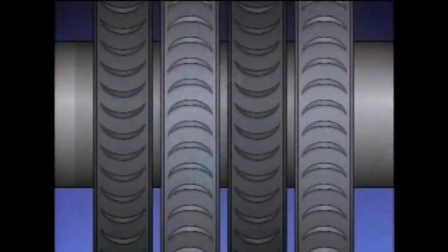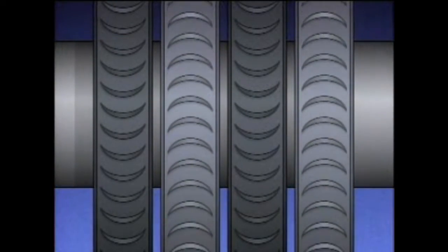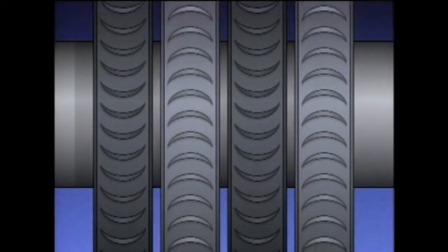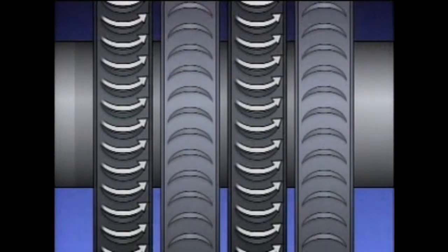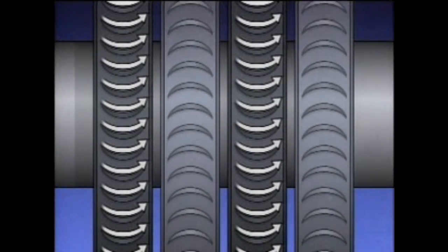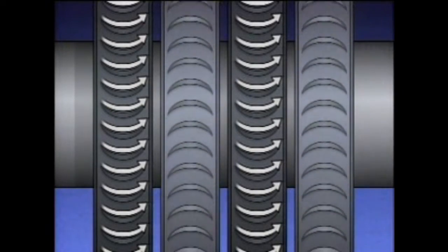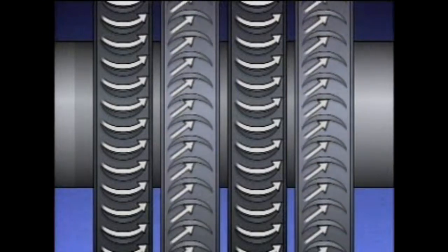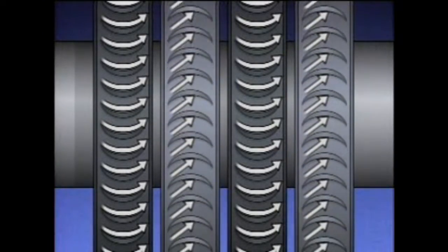Impulse blades work in a manner similar to the blades of a pinwheel. Air traveling in one direction strikes the pinwheel blades and pushes them out of the way, causing the wheel to turn. With turbine impulse blades, a similar thing happens. This simplified illustration shows the configuration of turbine impulse blading, with the rotating blades and the stationary blades or nozzles. As high-pressure steam is forced through the stationary blades of a diaphragm, it speeds up. The steam striking the rotating blades causes the wheel to turn. Since the wheel is attached to the shaft, the shaft also rotates.